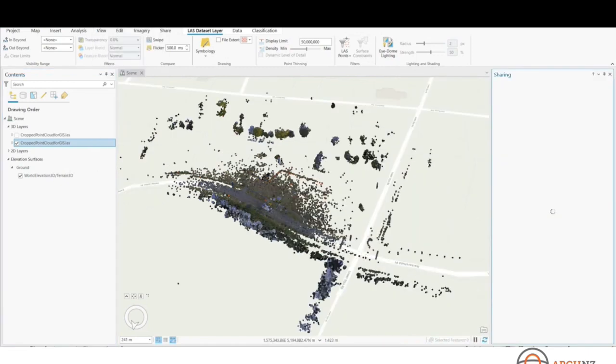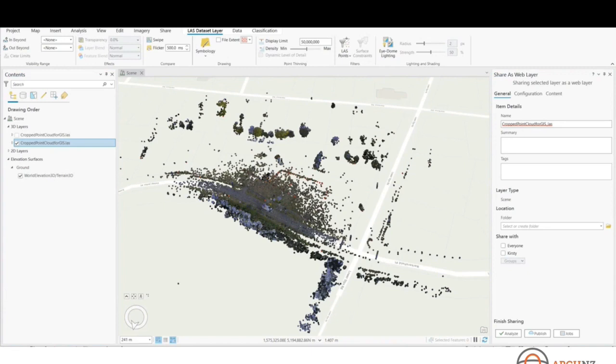But to get it to an online digital twin, an online twin in ArcGIS Online, you just need to get a scene layer package. So what I was showing before was just going to export a scene layer package or clicking the publish online option. So this is an easy way to share your point clouds with a bit more surrounding information on them. You could also do this same process of just publishing it online as a web map from the Arc desktop, assuming you have your ArcGIS Online account set up and everything.